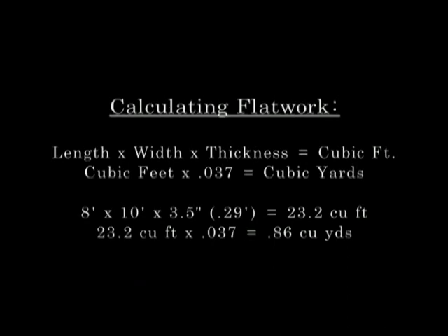You can then translate that into cubic yards by multiplying it by 0.037. As you can see in the example here, an 8-foot by 10-foot slab, 3.5 inches thick, would equal 23.2 cubic feet, or 0.86 cubic yards of concrete.